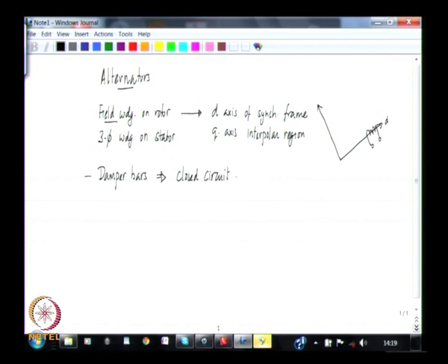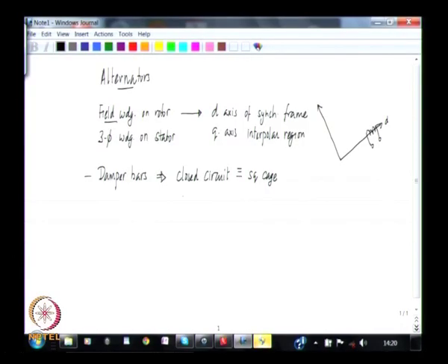It looks like, we have seen, the squirrel cage of the induction machine, and since the rotor rotates at synchronous speed and the field of the alternator energized by the stator also rotates at synchronous speed, there is no relative movement between the air gap field and the rotor, and therefore this squirrel cage, so to say, does not have any induced EMF, and therefore this arrangement is normally equivalent to an open circuit under steady state.